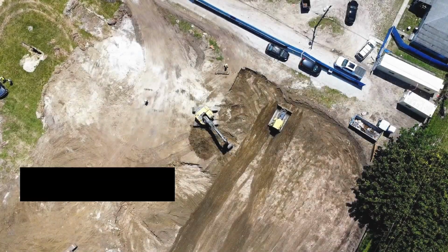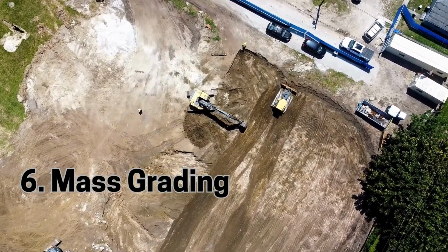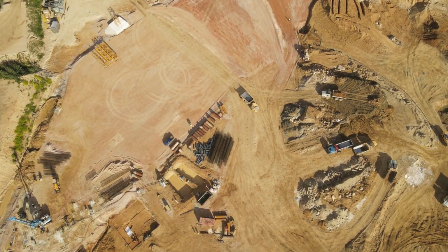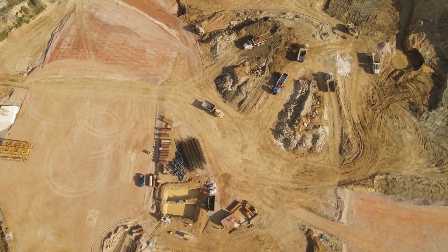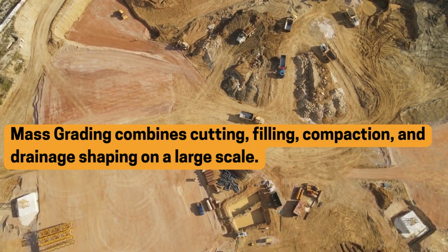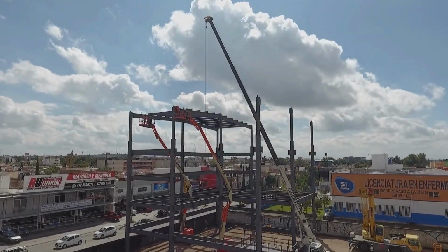6. Mass grading. For large-scale projects like airports, industrial parks, or highways, we use mass grading. Here, massive volumes of earth are moved to completely reshape the terrain. This method combines cutting, filling, compaction, and drainage shaping on a large scale. Modern mass grading often uses GPS and machine control systems for precision and efficiency.